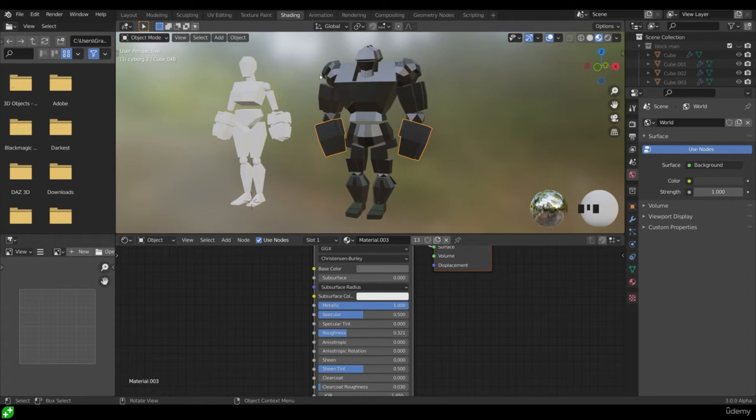Now, if all your objects don't share that one material, have a quick think how you could link those materials. So the clue was obviously in the way I said it. We're linking the materials together, so if I select all of them, my active object is the one highlighted in yellowy orange, not the more reddy orange, and that's the one with material 3. I'll rename this to metal so it's not confusing, and to copy this object's material, the active object, onto the rest of the objects, we press Ctrl L and then link materials. Obviously they're already the same, but just in case yours weren't. So pause the video and make your whole object a metallic color.